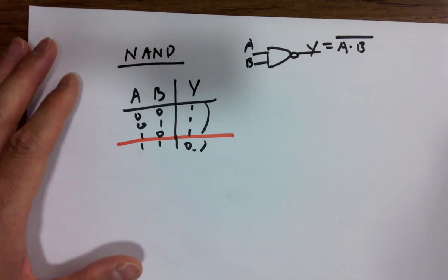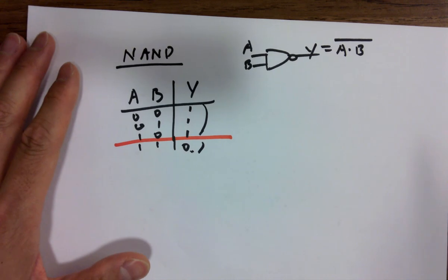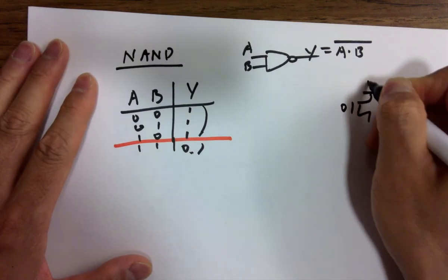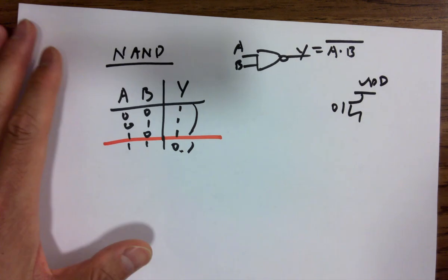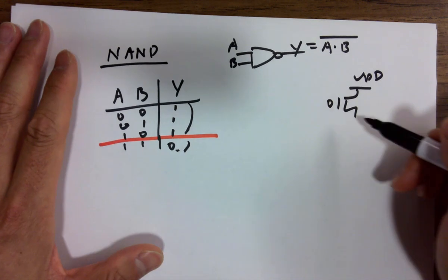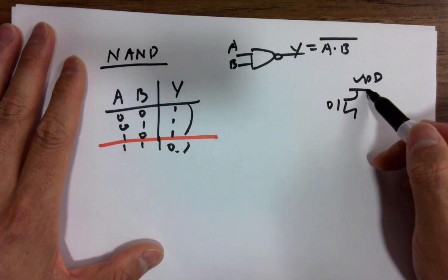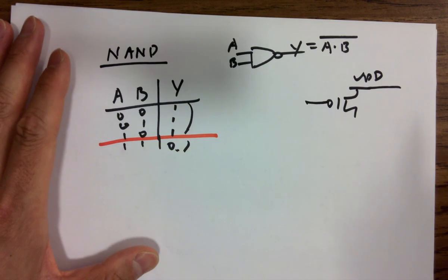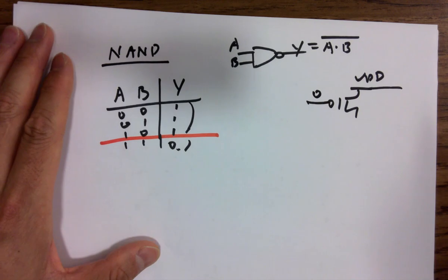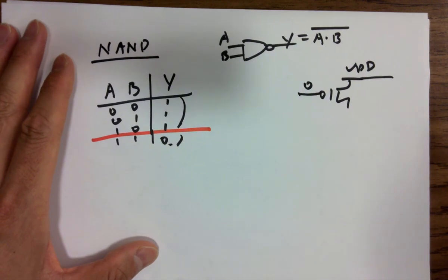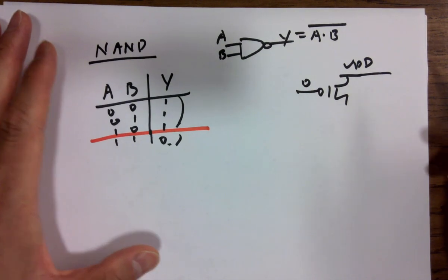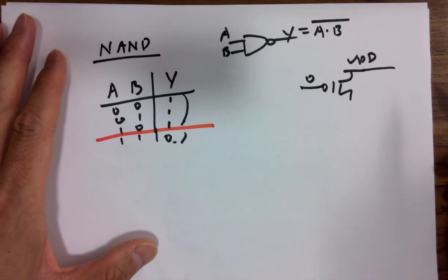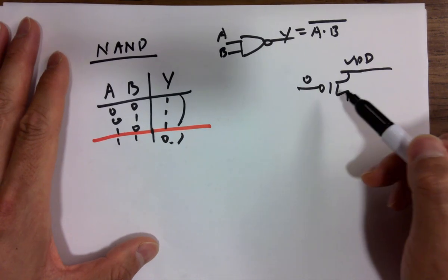So how do we do that? A PMOS, you need a 0. Remember that? Because PMOSes are good at passing ones, we place the PMOS on the top, directly connected to VDD, and we need a 0 to turn it on. Do you agree with that? Yeah. Why? Why is that? Why will this turn it on?